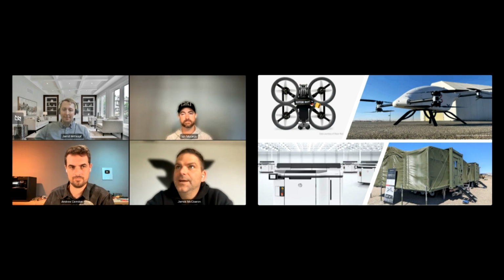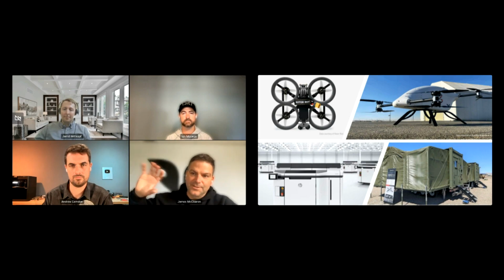The other thing that is super wow and just coming down the pike is augmenting MJF with carbon inserts. There's some pretty cool tech we're pushing with HP and some other folks. We're a tilt rotor, so the arm in the picture actually rotates. That aluminum part, the carbon fiber tube and the aluminum insert that goes in the aircraft, we will print and insert a carbon fixture inside.